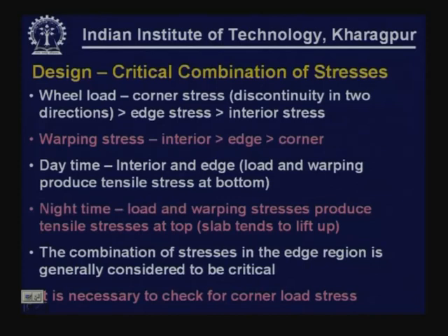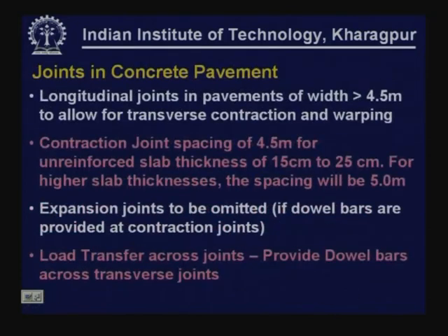The combination of stresses in the edge region is generally considered to be critical. So, it is necessary to also check for corner loads, although we are concerned about the edge region. IRC recommends that we should also check for the corner load stresses.